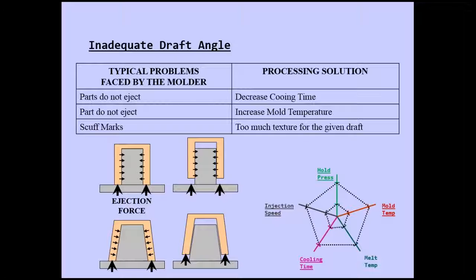So now you start getting a lot of post-mold shrinkage happening outside. What should have shrunk inside the mold tends to shrink more on the outside of the mold, and that's uncontrolled. If the diameter is critical to you, then you can control that dimension inside the mold by letting it shrink to a certain point, and then ejecting the part from there.